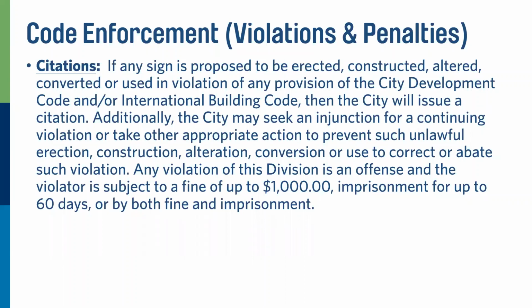We literally have one where we are doing the plan review at our table, look across the street, watching the sign get installed. Literally. So we stopped our plan review, walked across the street, and asked them what they were doing. Well, we're installing our sign. It's like, well, please stop and take it down. The reason why is because what they were planning on doing was not what they had drawn. Their drawing did not match with how you could literally install it.